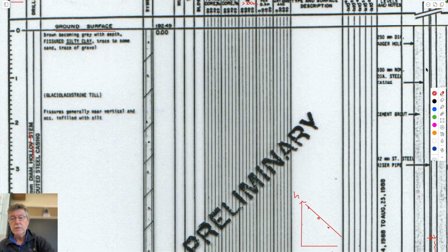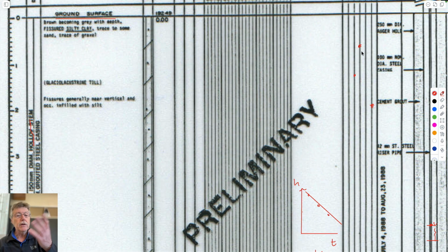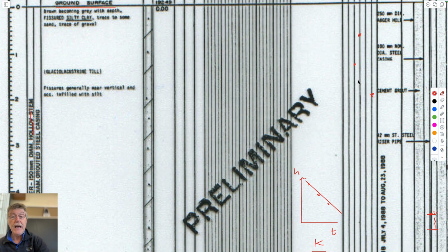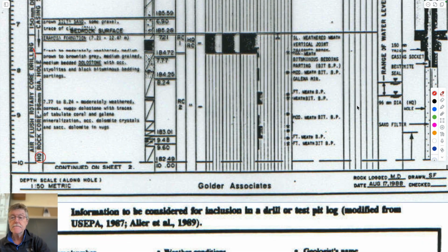So typically in these completed holes, to get the most bang for your buck, you'd want to do an in situ permeability test to be able to measure that. And that's of course what this column is here, to plant that on the log. So if you did measure that, you just put the magnitudes on here. So this represents the record of everything that goes on in the hole, and this is the cameo of what you've seen in your Smithville assignments, what the stratigraphy looks like.